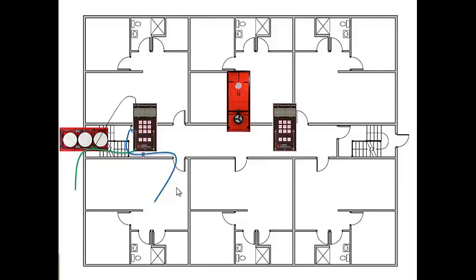And then we'll turn that one up all the way. And then on the third fan, we'll use the speed controller to get those blades spinning, and then we'll uncap that fan to make sure the blades aren't spinning backwards, and then we'll set that gauge to cruise 50 pascals, and we'll have to remember to turn that speed controller back all the way down to make sure that we're accurately getting our cruise number.